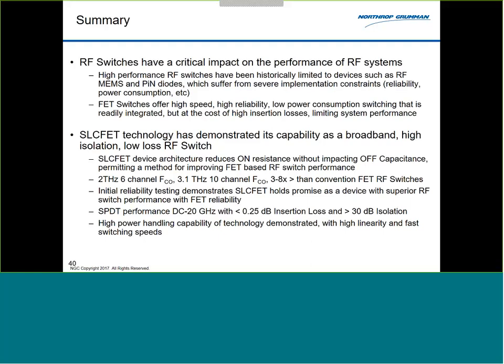So the question was, are most of the power losses conduction losses, or I assume you mean like switching losses? Yeah, so for RF systems, unlike power switches, it's mostly conduction losses. That's just because the switches, in terms of the size of the devices we're talking about, are not that large. And so the amount of charge that you're pushing in and out of the device in order to turn it off and on isn't that great relative to how much power is flowing through it, and so that's where I really see the power dissipation.